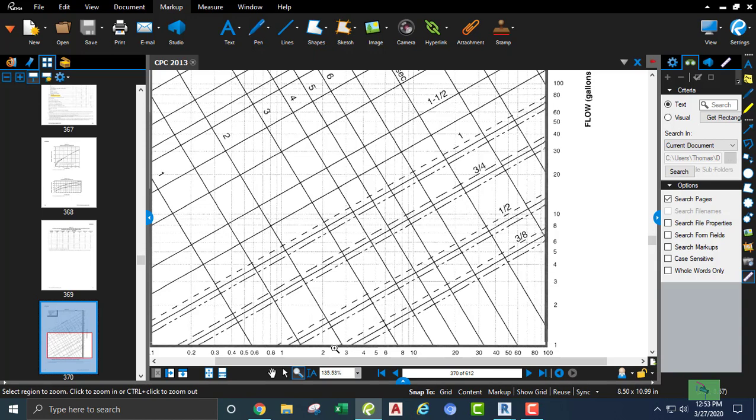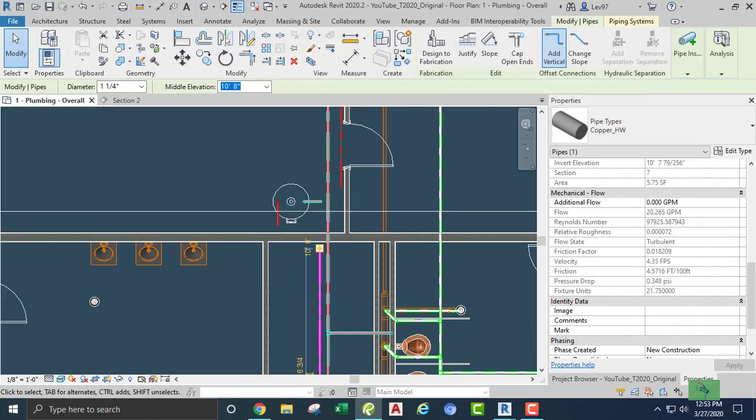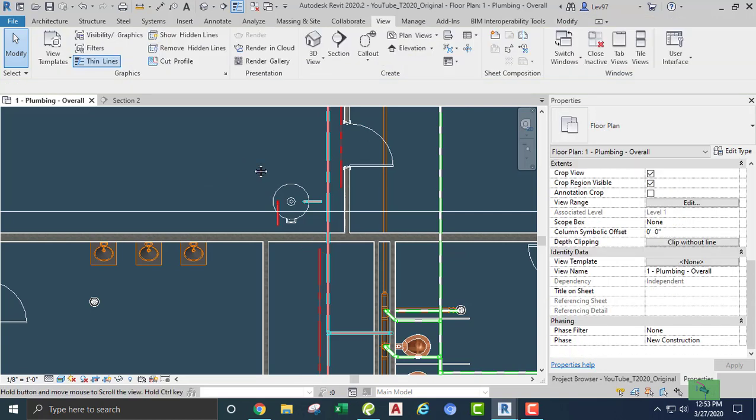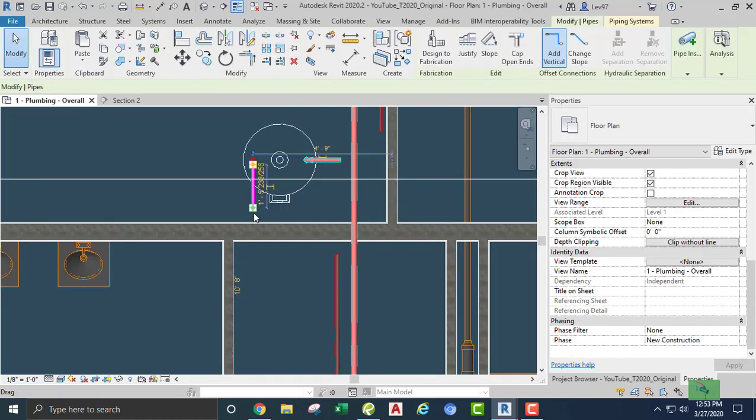A recirc pump. Okay, so let's use, so we're not bad. I mean, the velocity is 4, so it's not that bad. We're about right in there. 1 or 1.25. It's not science. It's based on a Hunter's curve anyway, which is back in the 40s sometime. So things have changed. So I think we'll be okay. 1.25. So let's just keep it at that. Not that I'm an expert at anything, but let's just keep it at that.